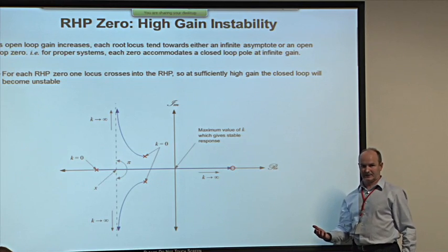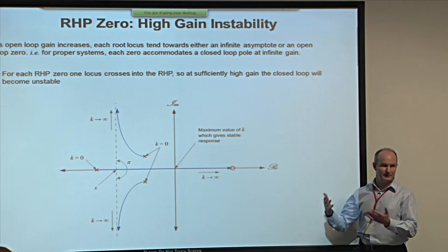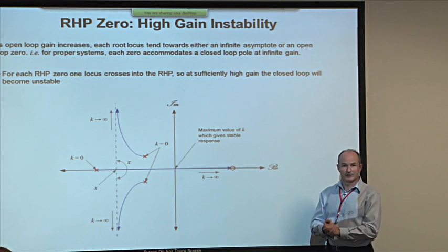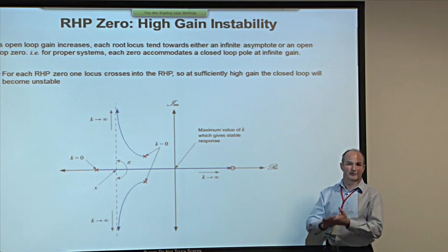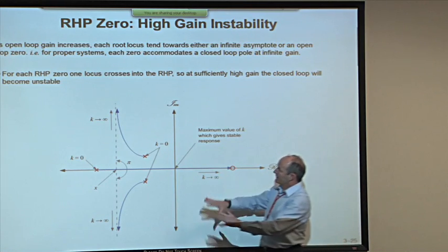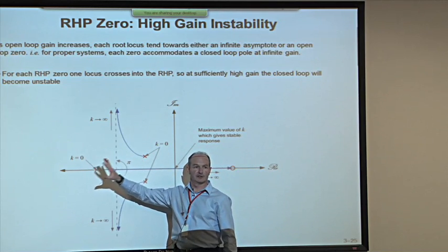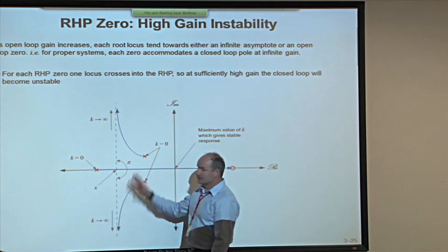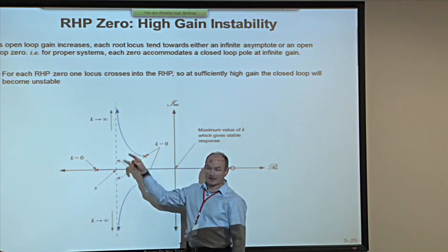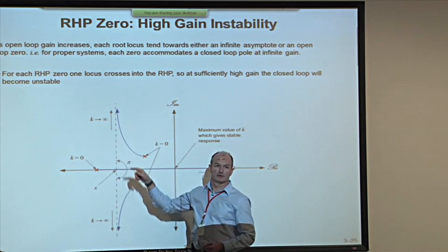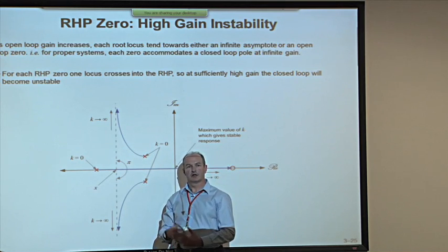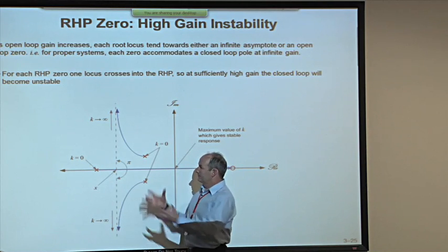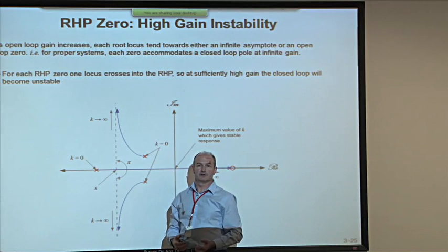So this is what you can infer from the root locus plot. How do you use it for design, right? There's one thing to infer information, it's quite another to use it. Well, what you do is you decide pretty much the quantities that you're interested in, overshoot, damping, all that stuff, and you mark out areas on the complex plane which you think are legitimate for you to place the closed-loop poles. Now, sometimes you can get the poles there by just changing gain, by moving them along the root loci until they're in that region. Other times you can't. You're inhibited because there are open-loop poles or open-loop zeros pulling the loci into undesirable regions.